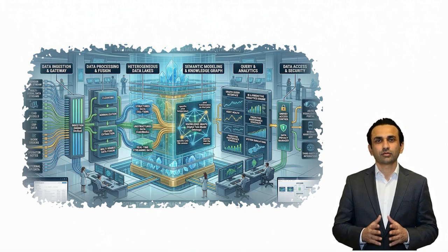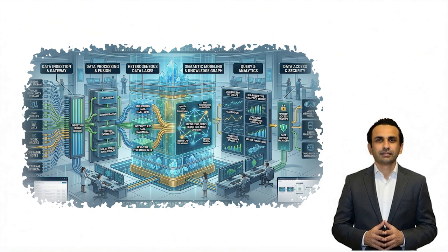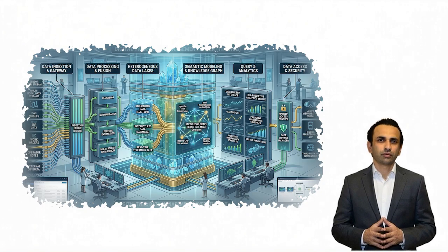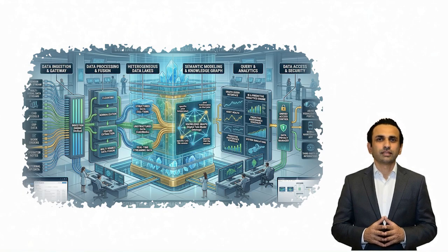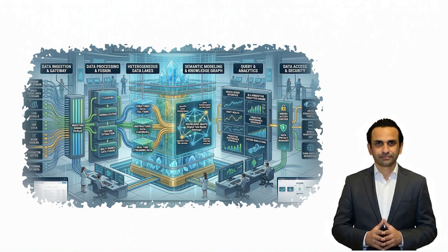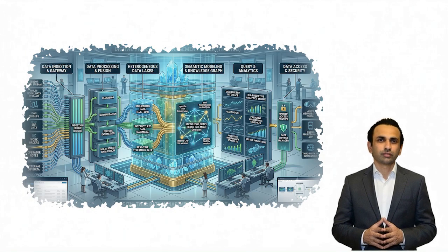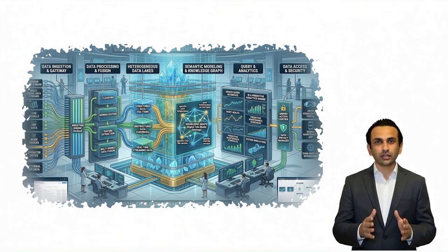This layer turns raw sensor values like temperature equal to 72 into meaningful context like supply air temperature of AHU3 on floor 5 at 10:32 am. Without context, data is useless. This is also where historical data lives, which enables trend analysis and learning over time.